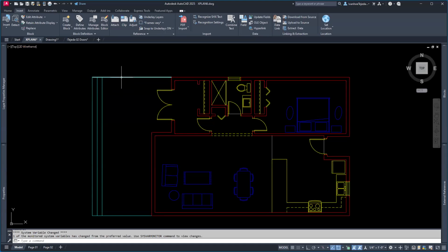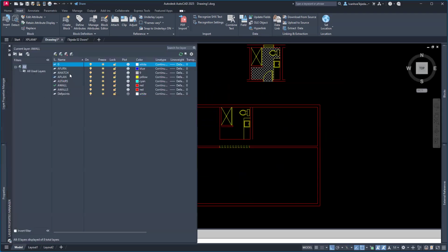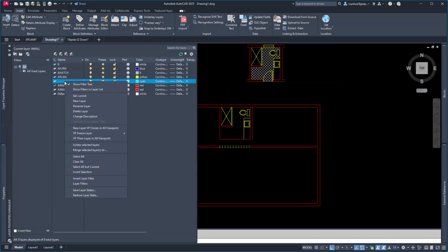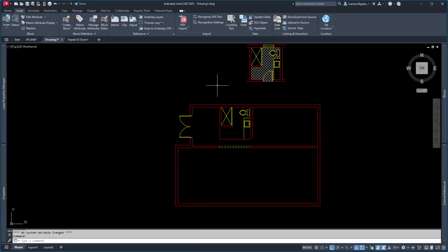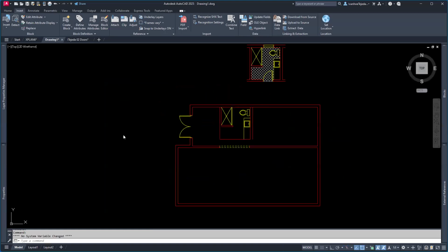If you already have the layers, I kind of showed you how to do the data mining with the Design Center. I want to show you something else here. Let's go back to the drawing. And just for kicks, I'm going to take this layer, my stair layer, right click it and delete it. There was nothing on that layer, so that's why I'm able to delete. But watch this. I'll go back to my drawing here. I'll just take this line and I'm going to do a control copy. I go over to my drawing and then I do a control V.